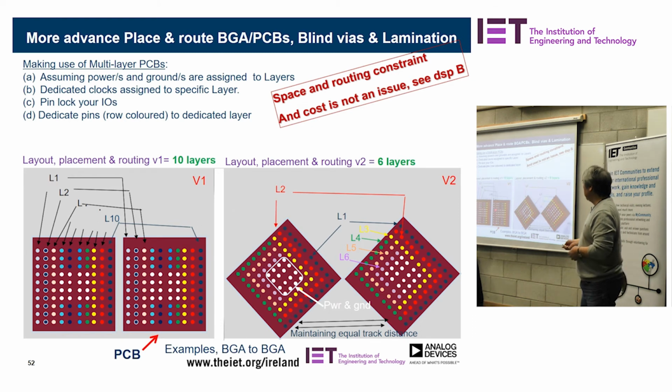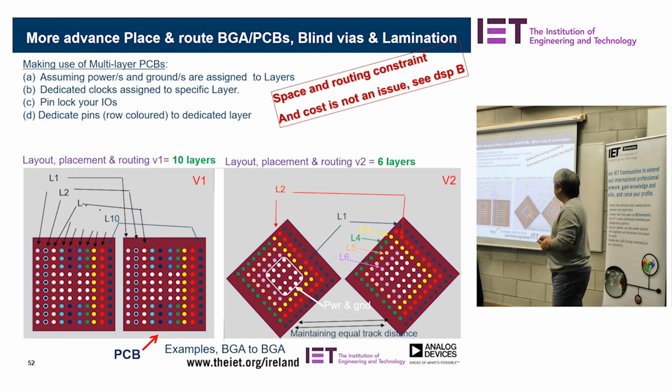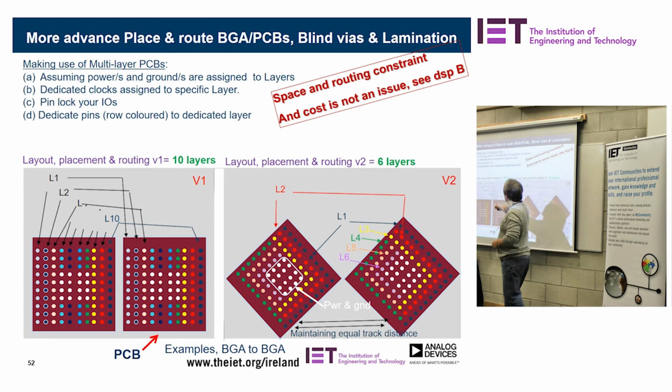For an easy one, if you want to maintain the length, you can connect this outer layer to this inner layer to the first layer, so they maintain the same track length. So if you connect this guy to this guy on one layer, and this guy to this one on another layer, they all maintain the same distance, but they're on different layers.